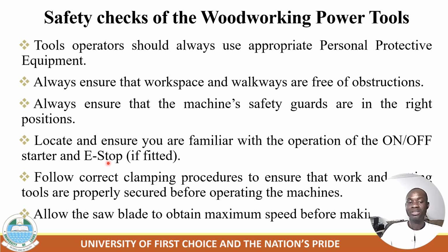E-stop means emergency stop. If fitted on your machine, know where the on and off switch and e-stop are located. Also follow correct clamping procedure to ensure that work pieces and cutting tools are properly secured before operating the machine. Allow the saw blade to reach maximum speed before making a cut.